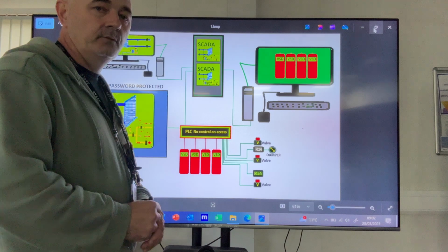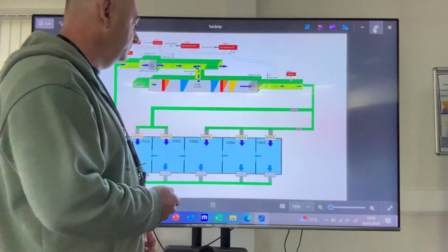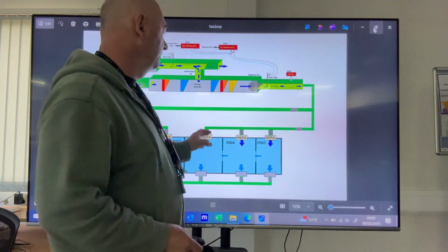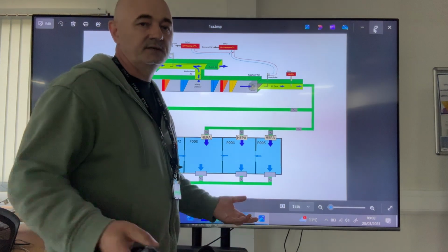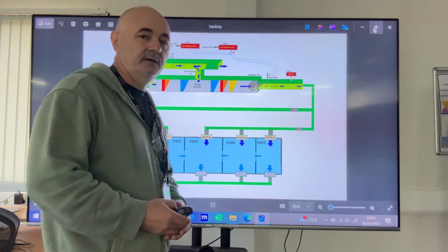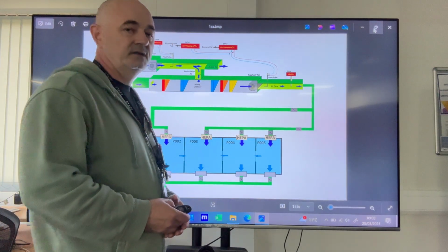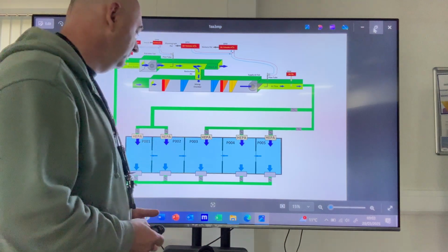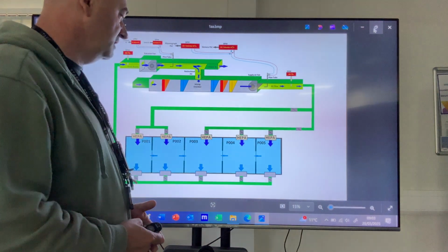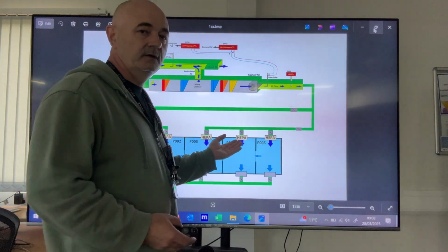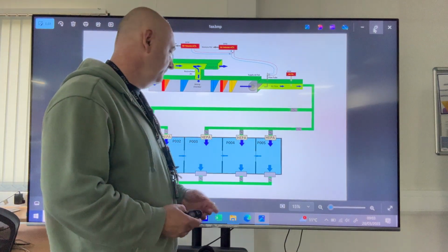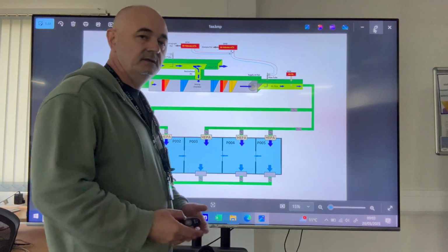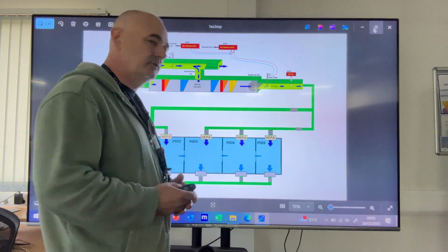The only thing we worry about is the distribution, because the dampers are manual. Anything that happens to the damper can disturb the change rates in a room, and we wouldn't have a clue, because on many occasions I observed that if something happened to an air supply damper, people will adjust the return, increasing the pressure in the room.